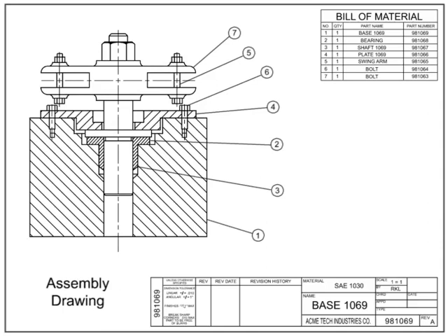Assembly drawings can show exploded views or section views. This drawing utilizes a section view to better identify each item in the assembly and to give an interior view of the part. Section lines are used to indicate the portions of the assembly that have been cut away. There are few, if any, hidden lines in an assembly drawing. Only the dimensions required to fully assemble the part or to be used as references are shown. In many cases, the order of assembly may be given in the notes.